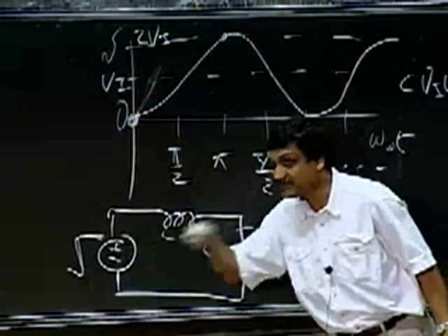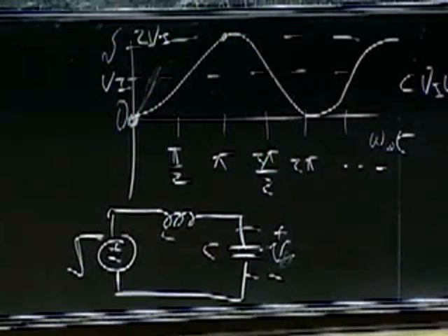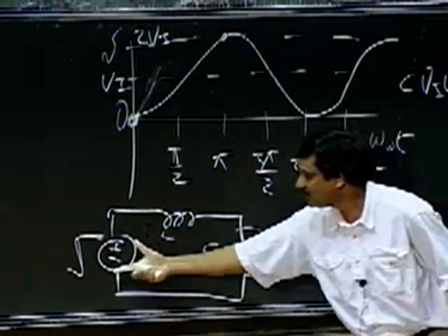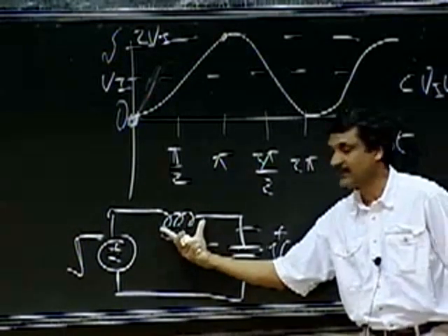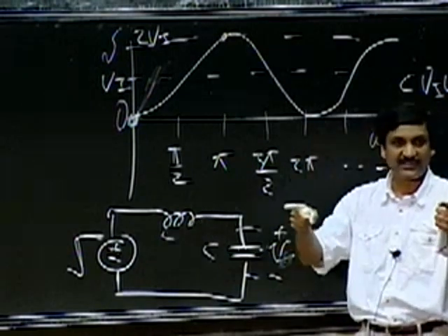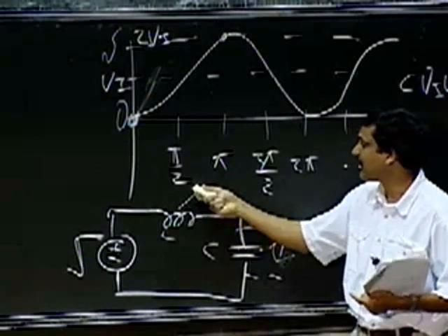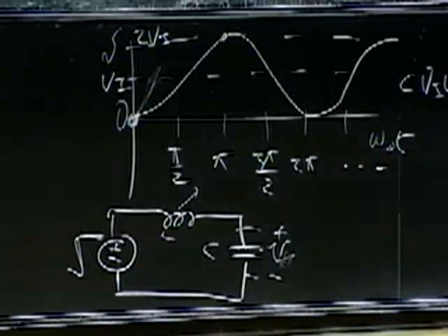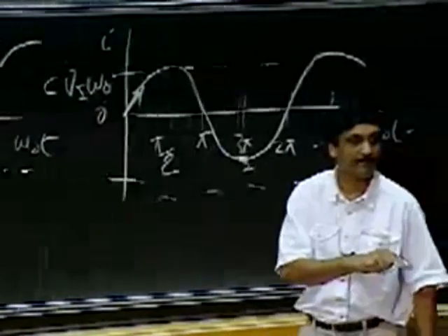Okay, so for the entire voltage here, KVL must be true no matter what. Those are the absolute fundamental principles from Maxwell's equations. So KVL must hold, which means that the entire voltage VI must appear across the inductor. So I put a big voltage across the inductor, and its current begins to build up.